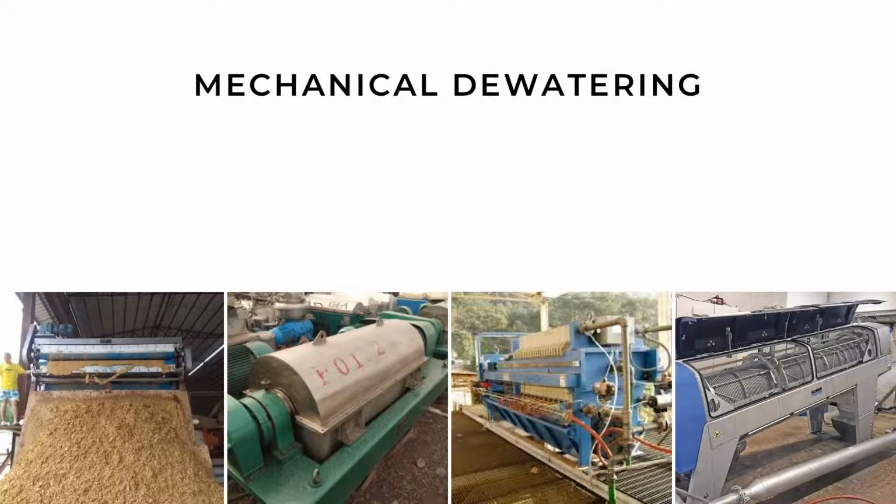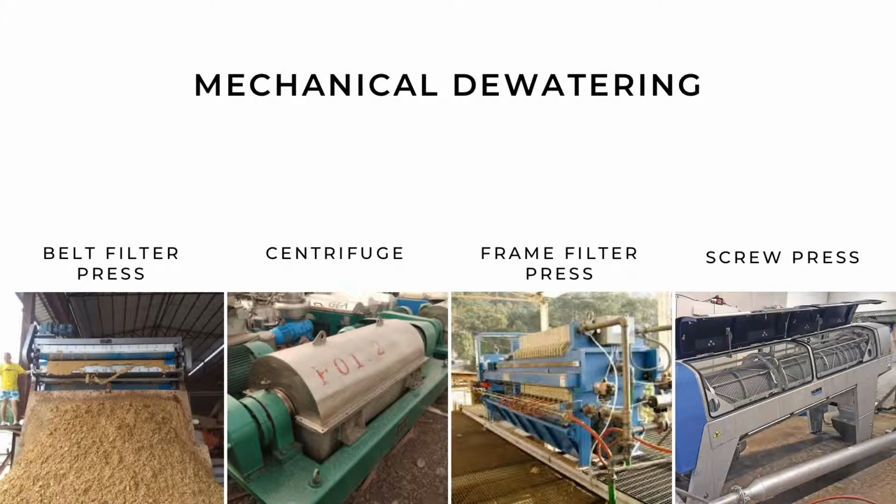Mechanical dewatering consists of the use of machines for the dewatering and thickening of sludge. 4 technologies that are widely used for dewatering sludge from wastewater treatment plants are the belt filter press, the centrifuge, the frame filter press, and the screw press. A preliminary addition of flocculant is recommended for all of them to facilitate the separation of liquid from the solid particles.